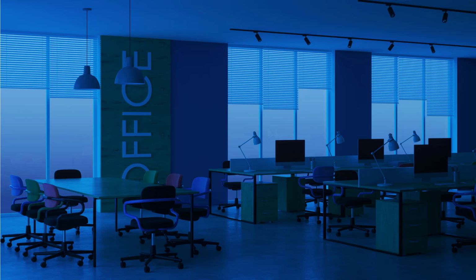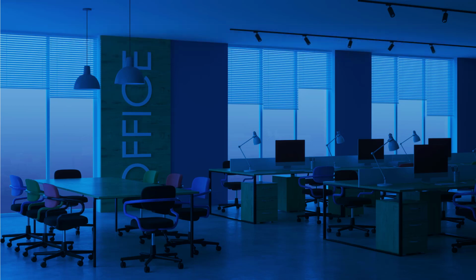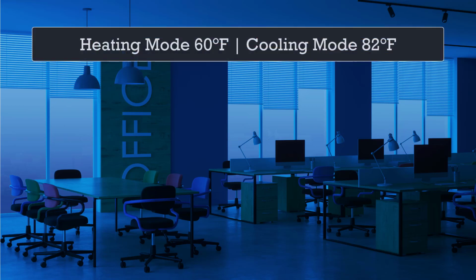Cooling and heating mode unoccupied temperature set point is referred to as unoccupied period setback or nighttime setback. A common unoccupied period indoor temperature setback is 60 degrees Fahrenheit heating mode and 82 degrees Fahrenheit cooling mode.